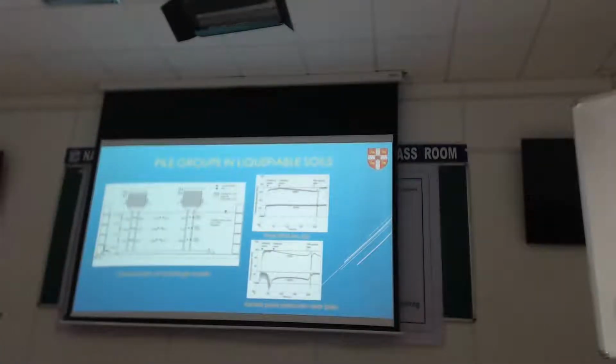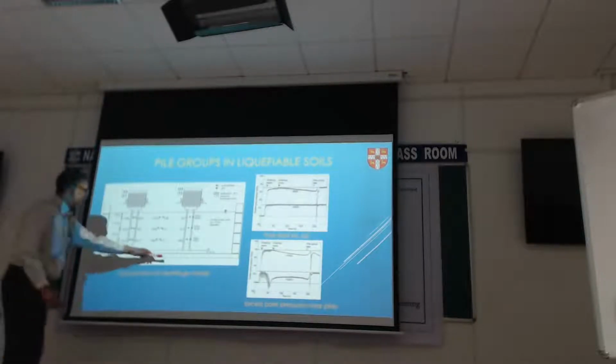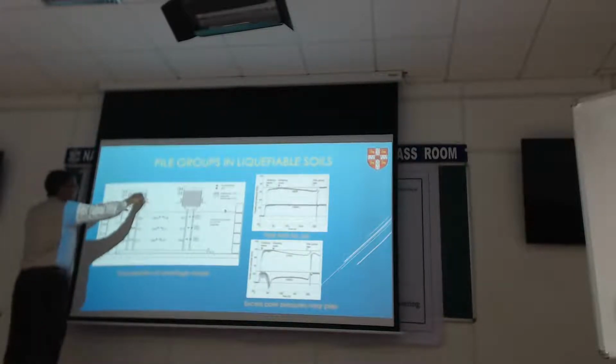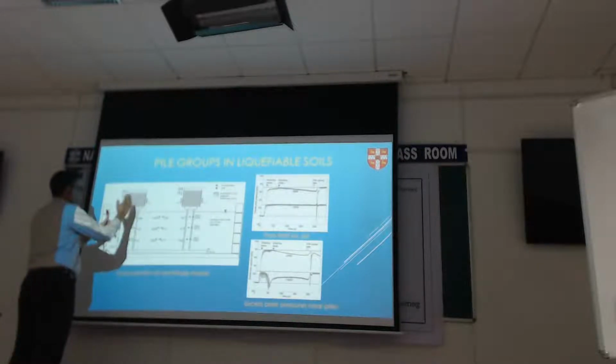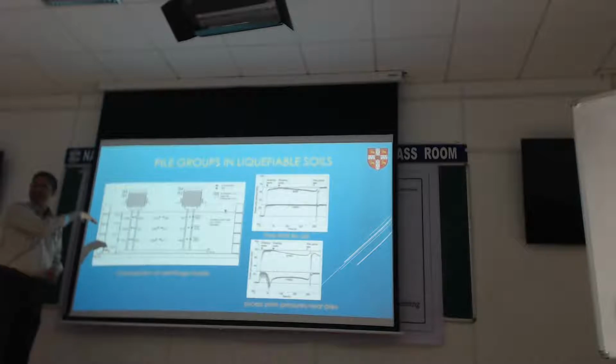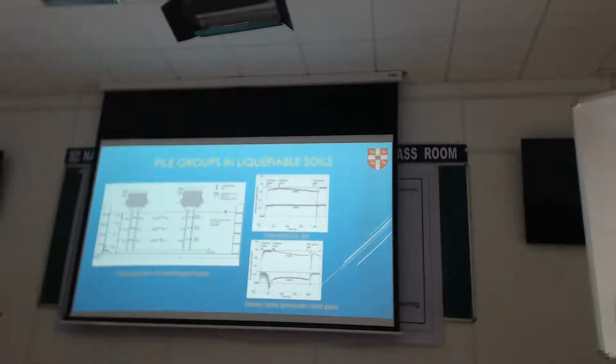So we decided to support the pile groups in the direction of shaking. This is a very unusual test to do. So we are shaking in this direction, but the pile heads can't move. There are supports on either side. And we have PTFE so that the pile group can slide in and out of the plane of the paper.